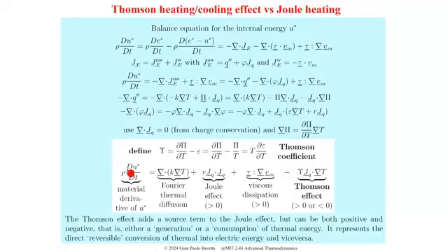So you should think of this as the equivalent of the Fourier equation of conduction. This would be rho Cv times the derivative of the temperature with respect to time. This is K times the Laplacian of the temperature, if K is independent of position, therefore of temperature.